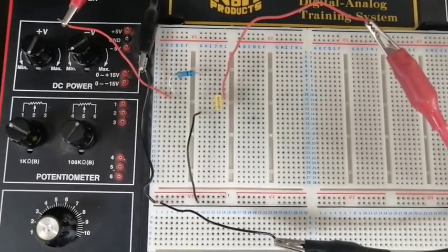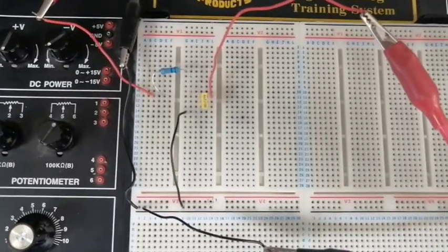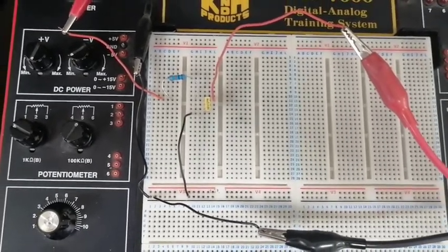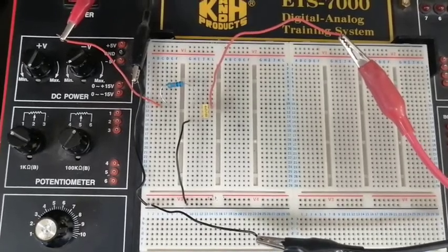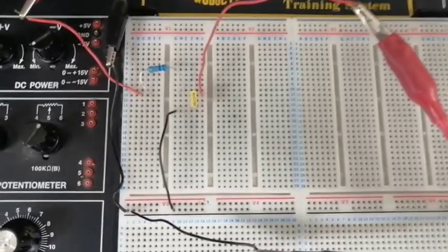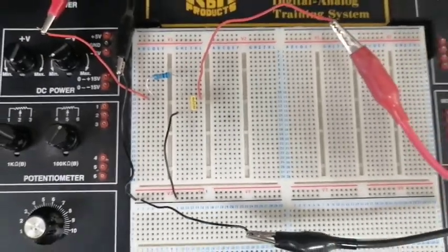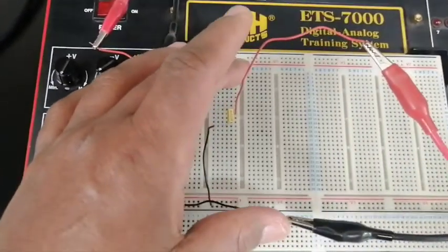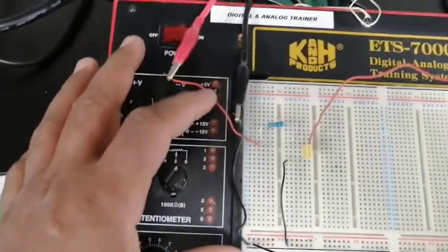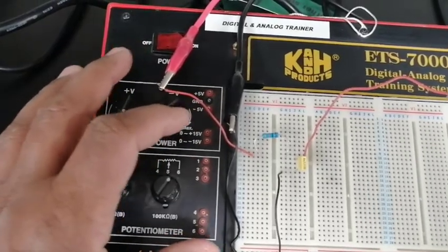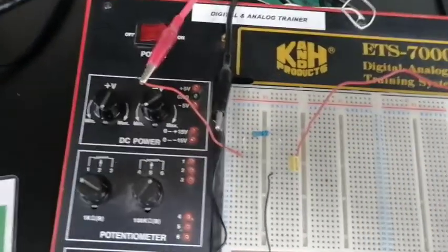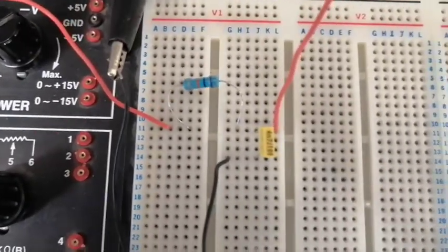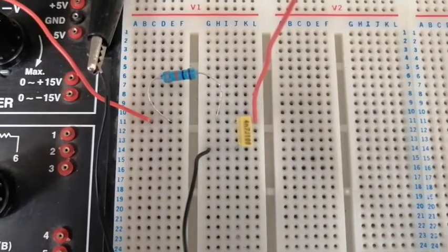So I'm going to take the output of this circuit, VC, during different delta of time between 5 microseconds and 900 microseconds. The connection is shown on the circuit. This is for channel 1 of the oscilloscope, and the input is taken from channel 1 of the function generator. The circuit is shown in this configuration.